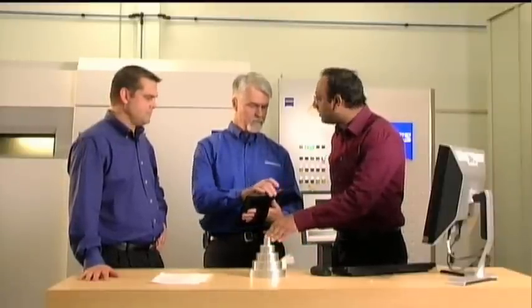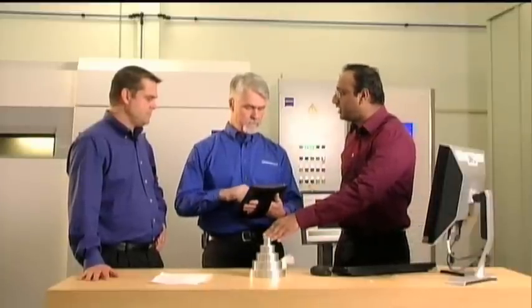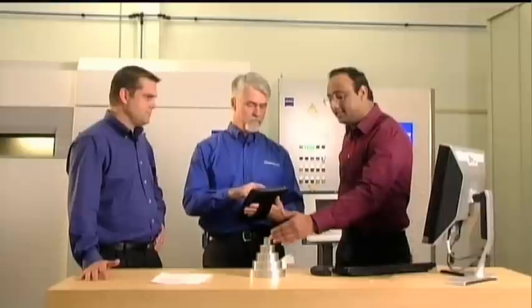Okay, all right. A question I had myself, you had touched on edge detection, and kind of the problem with X-ray is that as you get closer to an edge, the edge gets thinner, and so the X-rays are kind of blowing through it, and that's what's making the edge hard to see? It's not the fact that the X-rays are blowing through the part. Again, the amount of material that you have, as X-rays go through the part, they start losing a certain amount of energy because they are interacting with the molecules of the part. So the signal that is collected in front of the detector is based on the amount of material that you put in front of it and the density of the material.